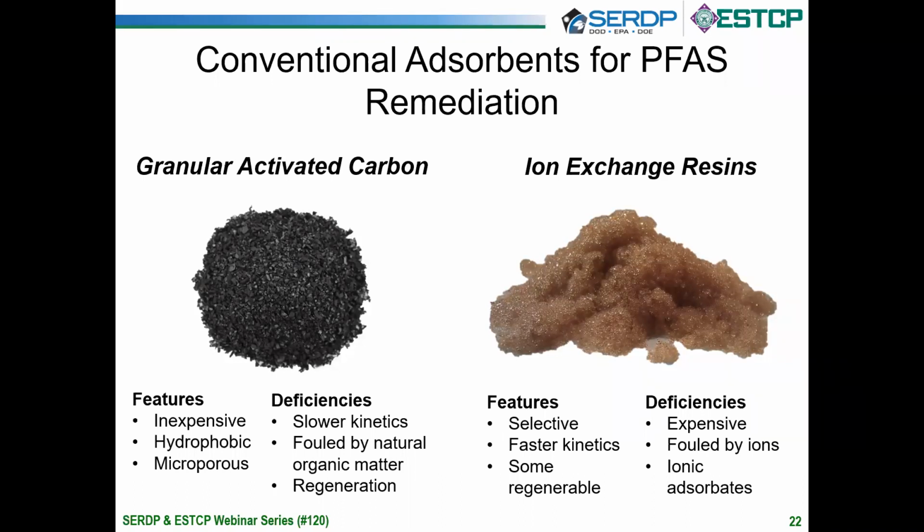On the other hand, ion exchange resins can be more selective for target adsorbates. They can exhibit more rapid adsorption kinetics, and some emerging ion exchange resins are regenerable. However, ion exchange resins are relatively expensive materials, can be fouled by inorganic ions in groundwater, and are limited to ionized adsorbates of the appropriate charge.